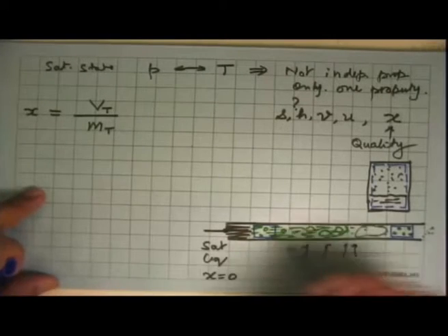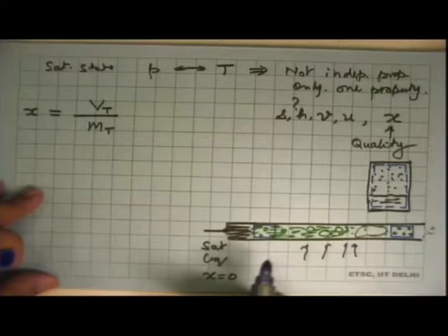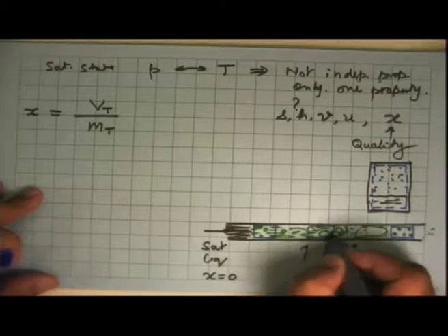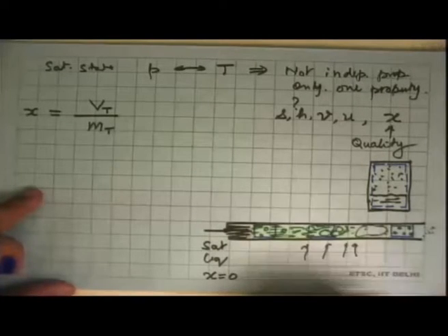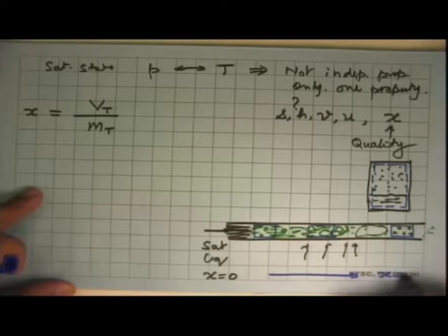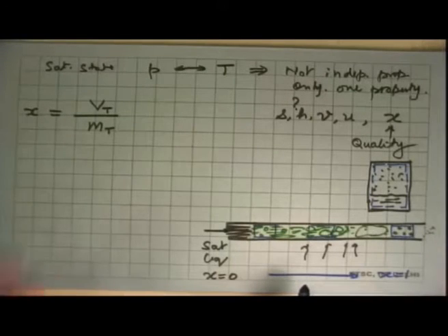In between, it's very irregular behavior, and we cannot really write equations and solve them. But qualitatively, we can say that if I take an element here, what is the dryness fraction? And we know that as this heating takes place, x goes from 0 to x equal to 1, and then if more heating takes place, the temperature rises, and it is then a superheated vapor.